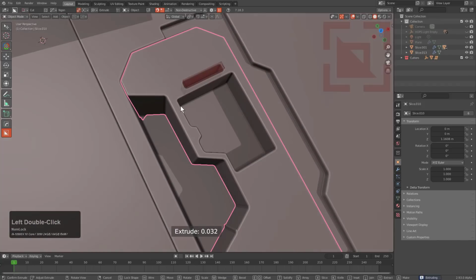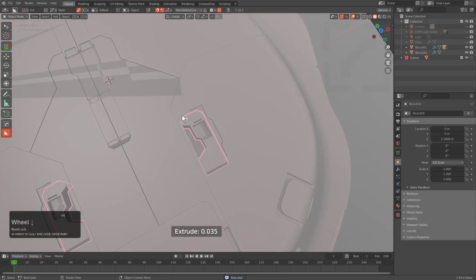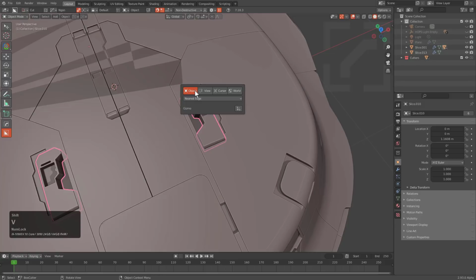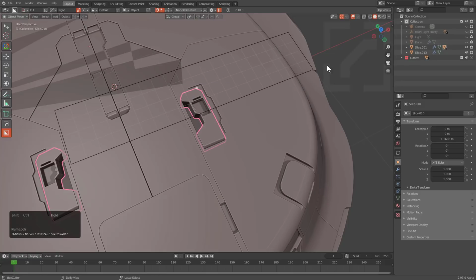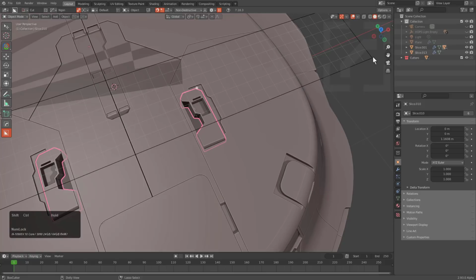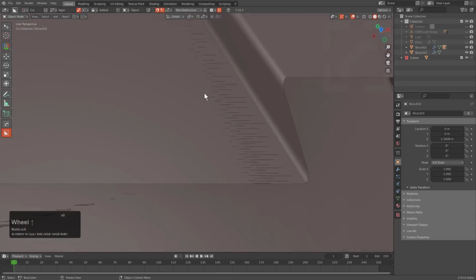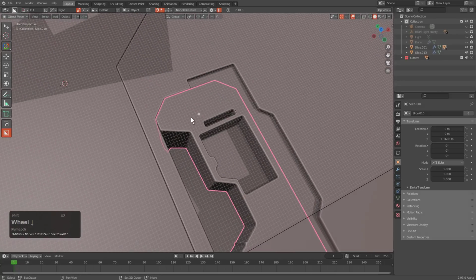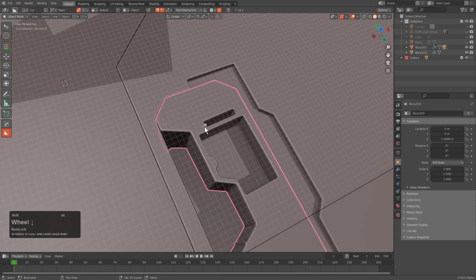this would normally just be the end of it and Blender would just be turning white and the session would end. And best of all, I can of course just press Escape to get rid of it, but at any time I want to, I can just align to an edge because I'm under Shift V nearest edge, bring my grid in, maybe even Shift right click, Control right click to drag it out, and just roll in an impossible amount, and zoom in on it, hold Shift and roll to adjust how many I need exactly.